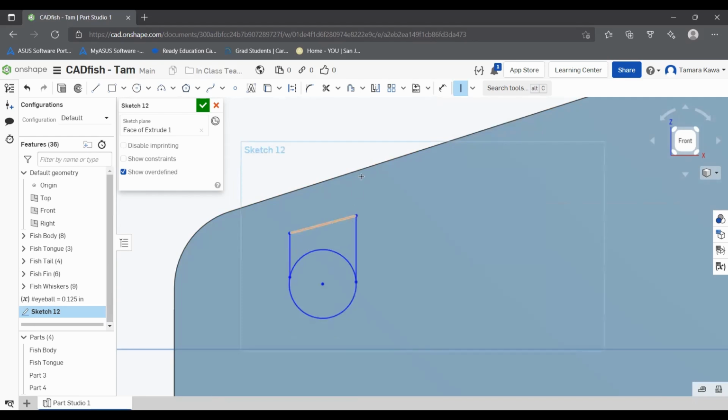Okay, here we go. Those are vertical. All right, let's make sure that they're not tangent, because every now and then, nope, not tangent. Perfect. All right, so now we go horizontal. And let's also make those two vertical lines equal to each other. There we go. And actually, let's make the top line equal to them as well.